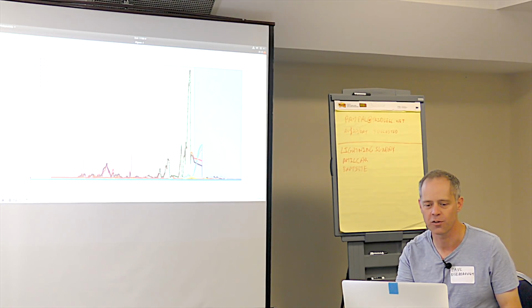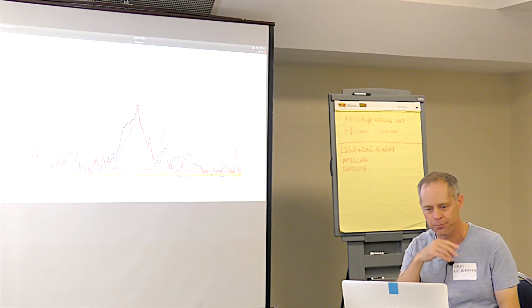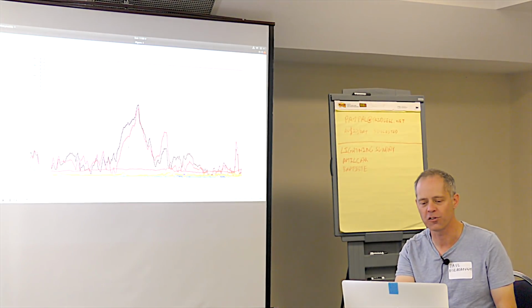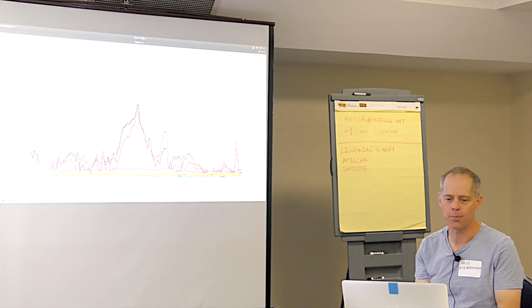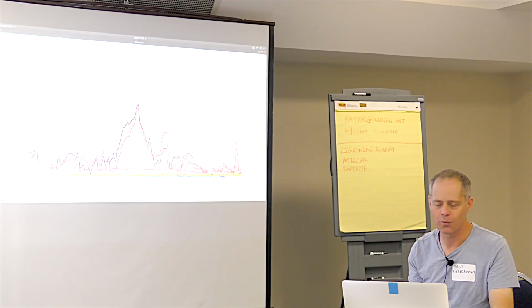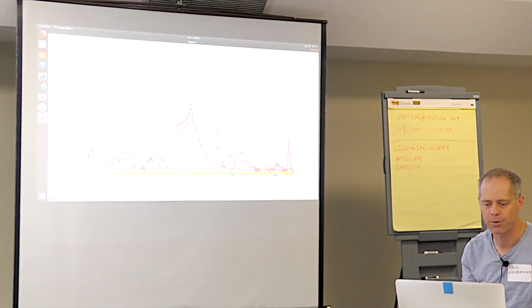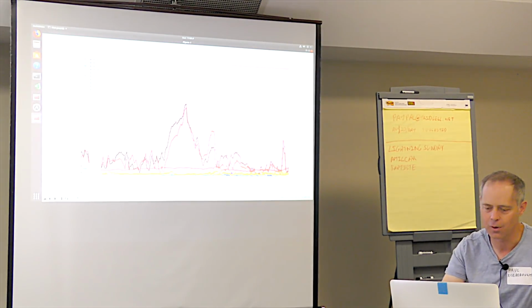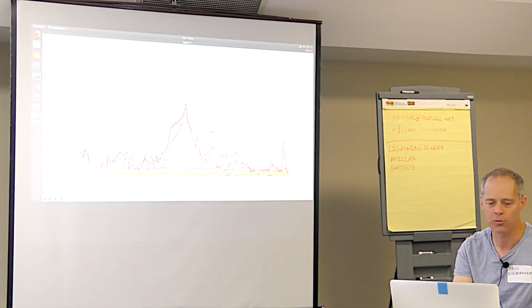In this instance, I think because the flight was in Loiter at the time, and they're looking at the copter, they're not looking at the ground station. We don't have any haptics or any sort of feedback to the operator on most systems for these types of errors. So you can see here that the GPS velocity errors on both IMUs, both EKFs, went high at a point in time in flight.